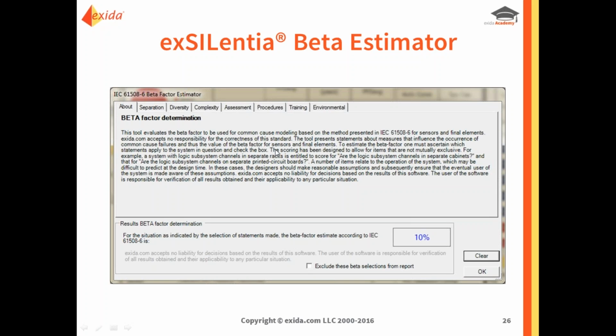There's another question here. Yes, this is also very interesting. There's a statement or question here: one of the organizations active in field failure study, like Exida and SINTEF, did a study where they suggested that the beta factors we're using, based on 61508, of 5-10%, are too optimistic.